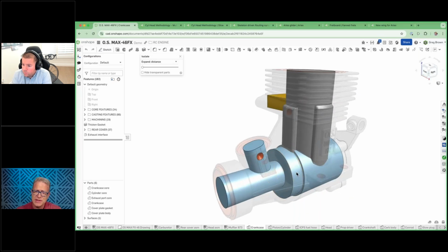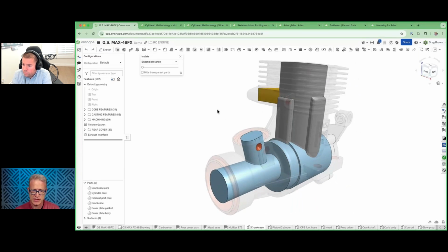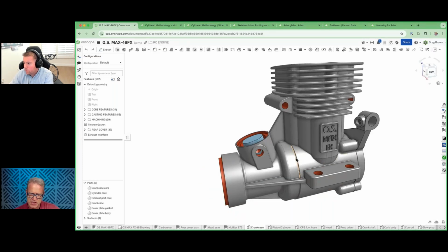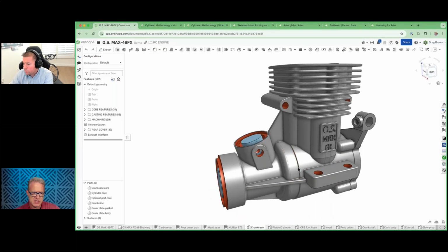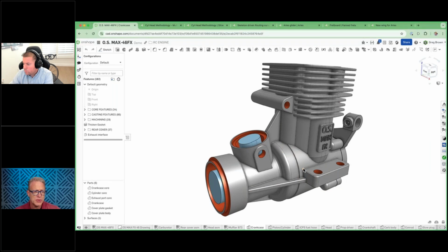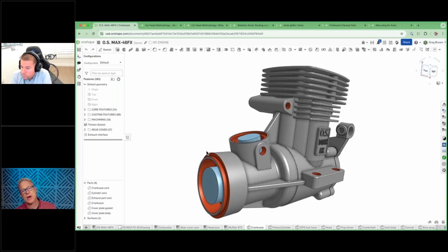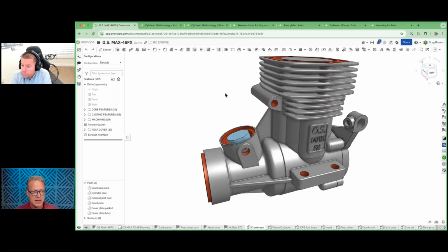Now, there's a number of other ones that are important too, and that is where you have bought-in components. So there's an R6Z bearing that goes in the front here, a sealed bearing, and then there's a 6902 bearing inside of here. These are things that I don't need to model as part of this part studio because they're an established standard, right? So the outer diameters of those are going to be core. So that is one way that I can say I'm going to draw the line as to how much I model inside a single part studio.